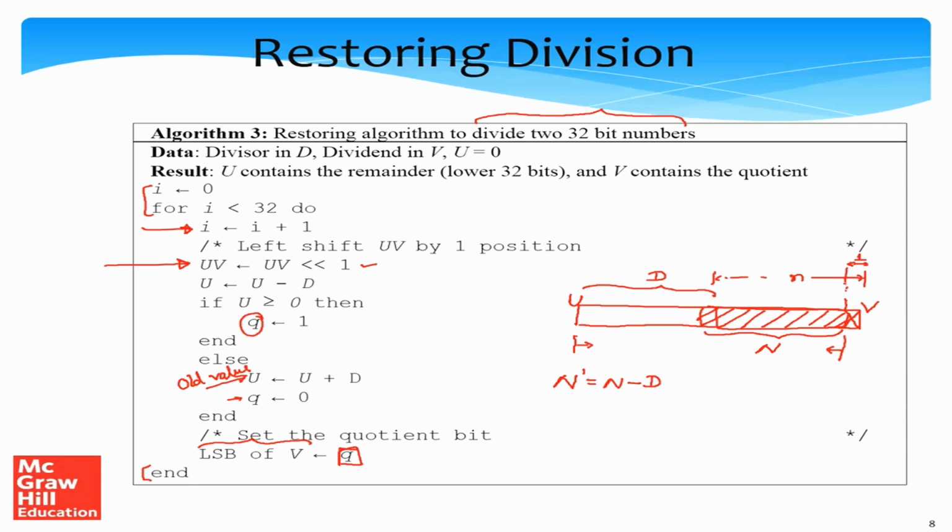Alright, so if you are looking at the screen, the divisor is n minus 1 positions to the left. So when I'm doing the subtraction, u is u minus d, what I'm essentially doing is that for this number, which begins from the beginning of the dividend till the end of register u, the beginning is all zeros, so let it remain in that fashion. So this number that I have, I'm essentially subtracting the divisor multiplied by 2 raised to the power n minus 1.